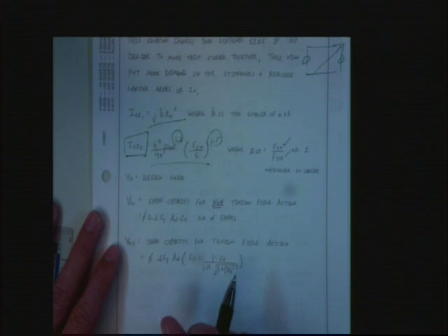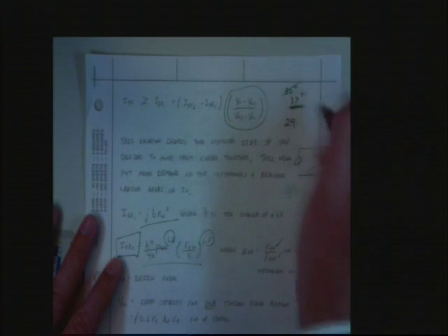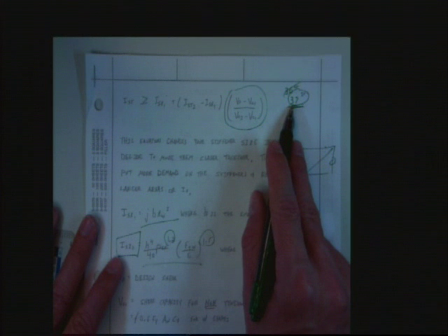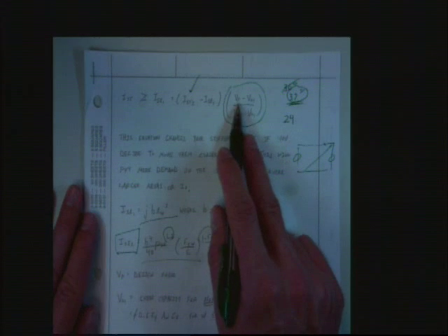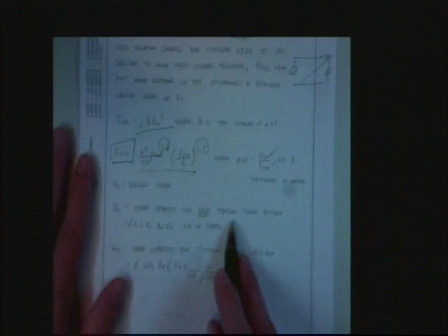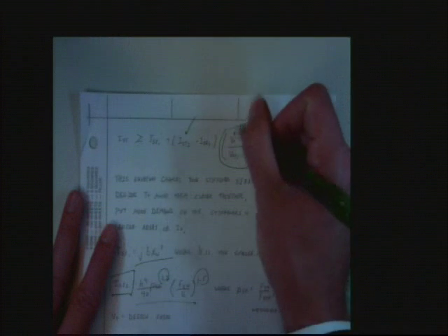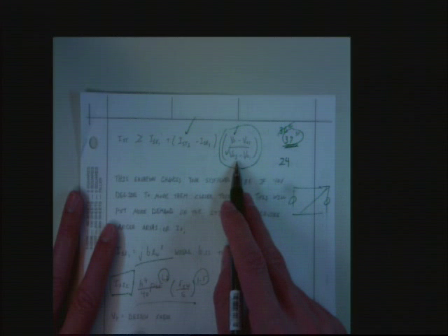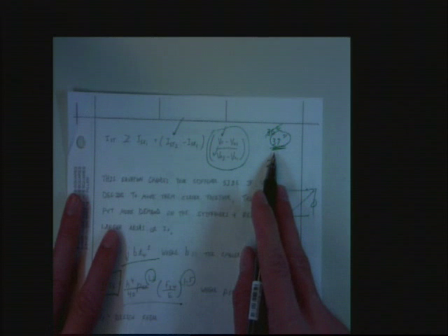I_st2. And what you'll find in this equation, and we'll see it in our example problem that we're going to work today, is that if you choose your stiffener size to be really close to what you need, then this goes away, these cancel out, and you're left with only I_st2 controlling. Can you see that? This is going to turn to 1. What's this? Well, this is your shear capacity minus your capacity with non-tension field action, divided by the capacity with tension field action minus the capacity with non-tension field action. So if this is very similar to this, this becomes 1. The shear you're designing for is close to the shear you're providing. That's only the case when your stiffener spacing is very close to what you designed.